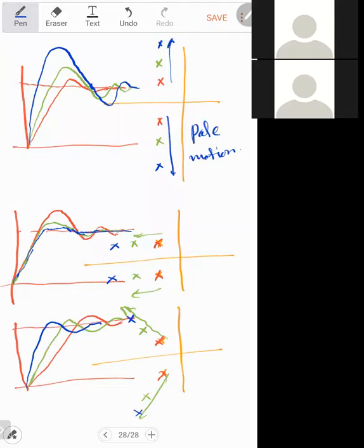In the first case, if you increase the imaginary axis, the vertical axis, the overshoot will increase. And in the second case, if you increase the real axis, this means you will reduce the overshoot, and they will have the same frequencies.